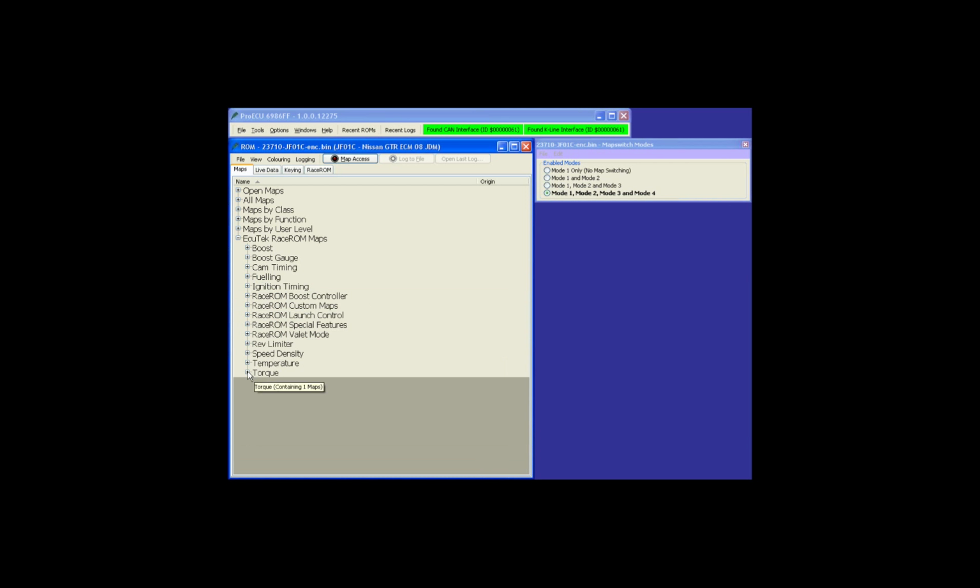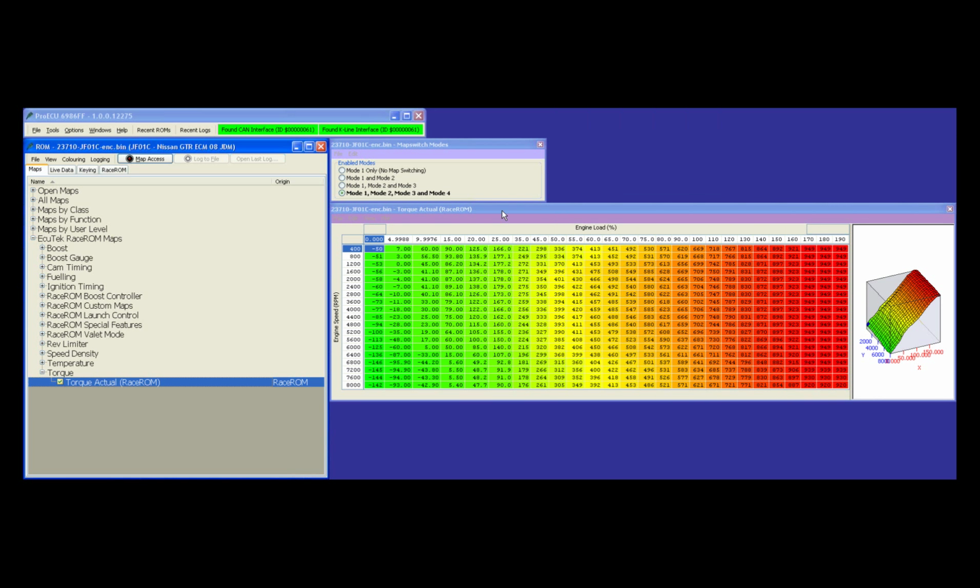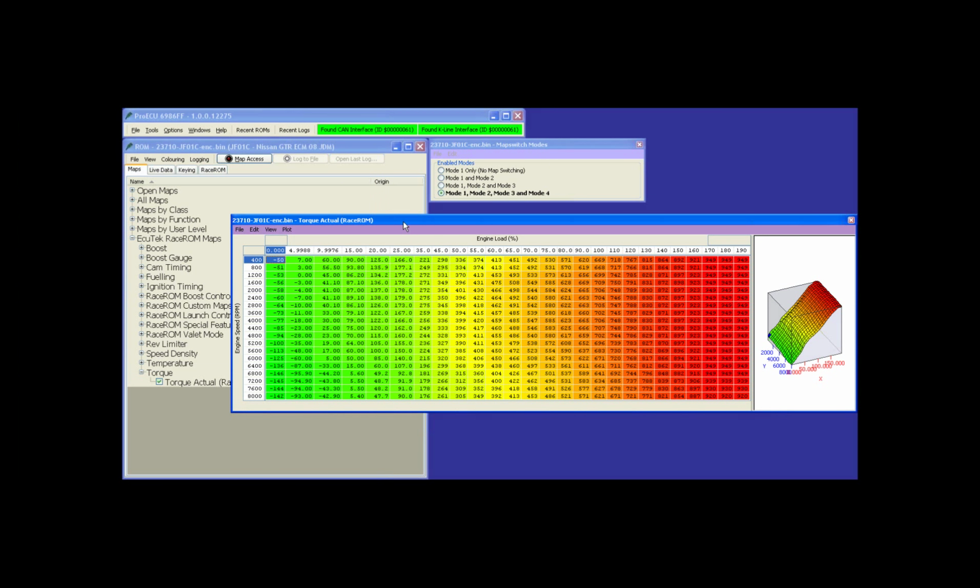We have a torque map, so we have a new high power torque map. A lot of the problems with GTR come from engine load and MAF rescaling, which make the torque value that's supplied to the TCM, the gearbox ECU, inaccurate, causing things like clutch slip, poor gear change decisions, gear changes that are too harsh, being whacked in the back on a shunt, not good for the gearbox, not good for the drivetrain, all in all. The new high resolution torque map will keep engine load more accurate and keep gearbox control so much smoother. Vast improvement.